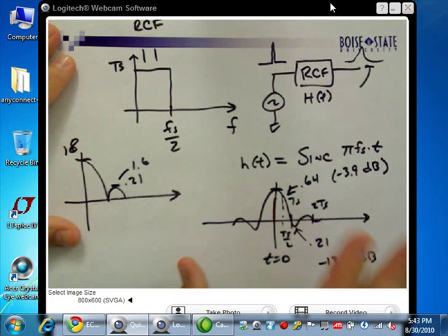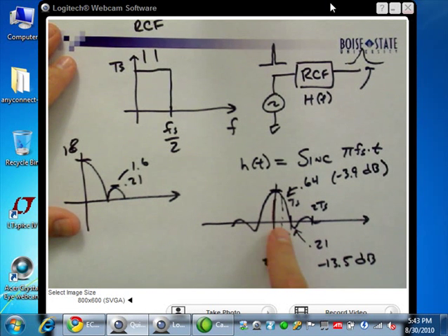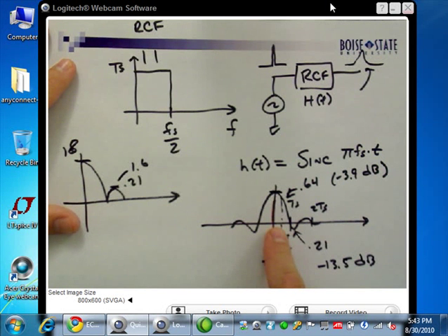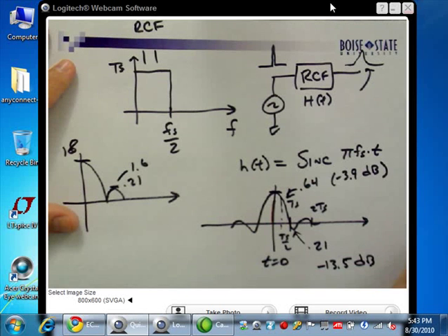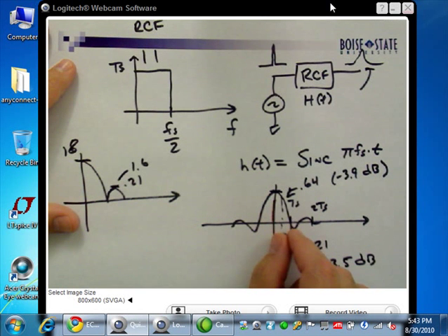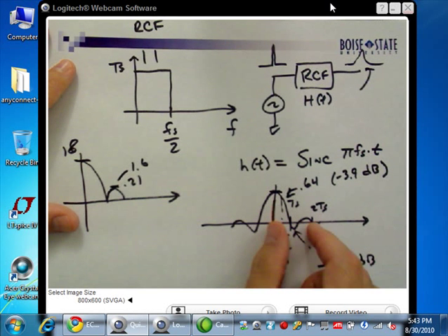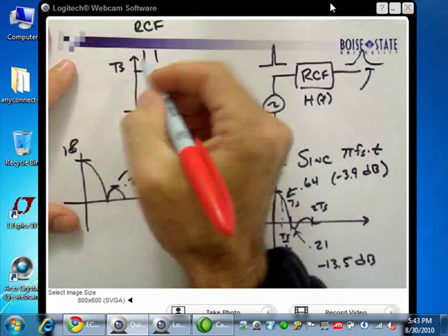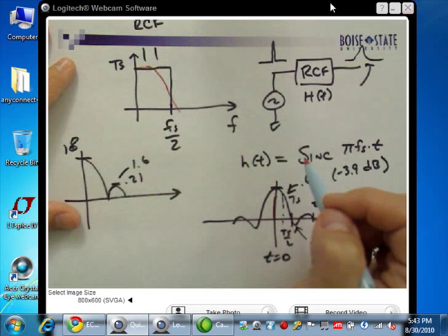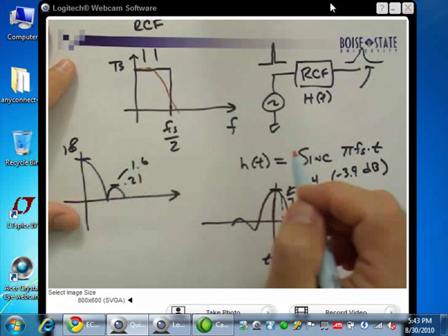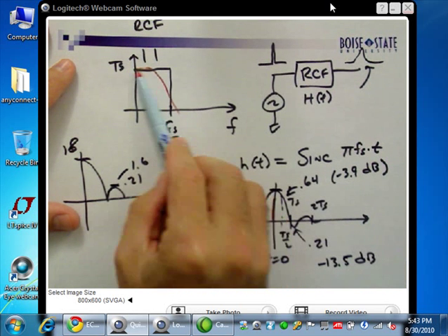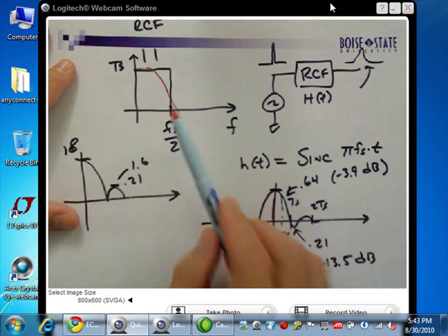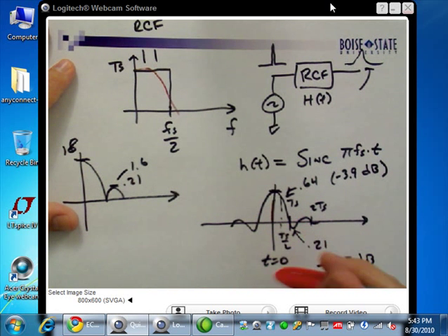So I can do one of two things. I can either increase the sampling frequency while keeping the bandwidth of interest constant, so that I oversample the input. So I go to 100 times higher sampling frequency. That means I can then use a filter which rolls off slower. Or I could reduce my input signal bandwidth. If I reduce my input signal bandwidth, then I can have a slower roll-off filter.